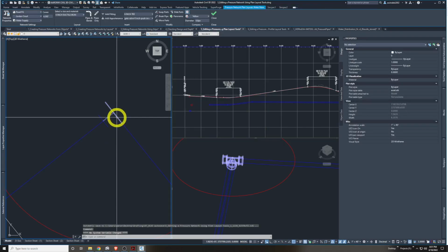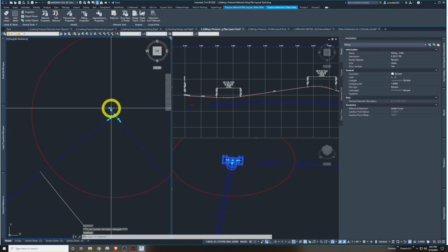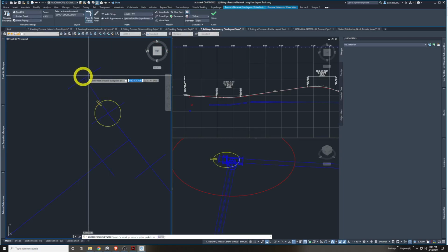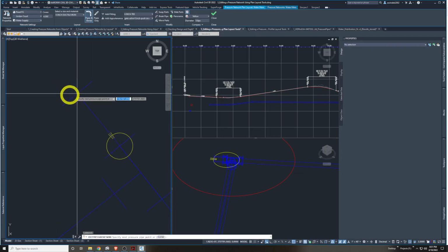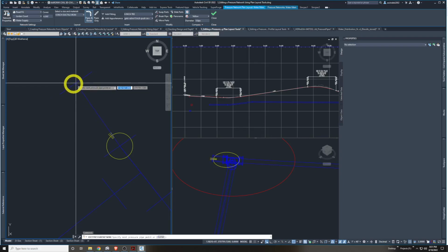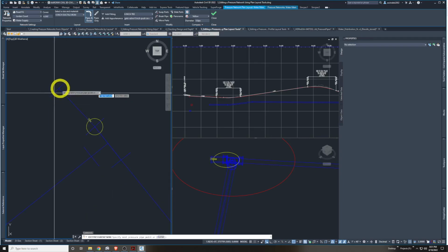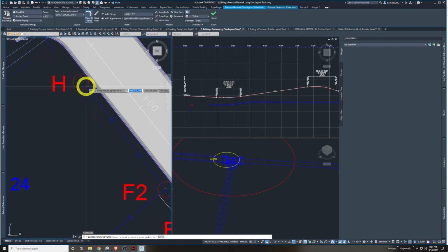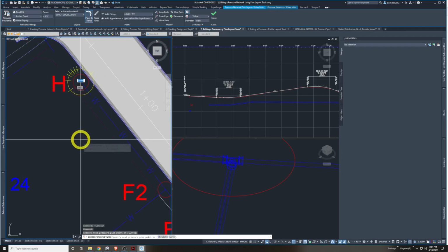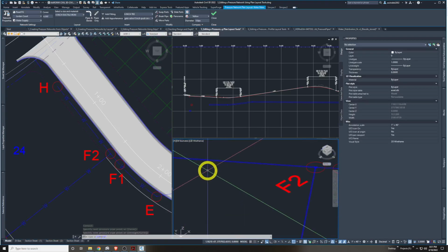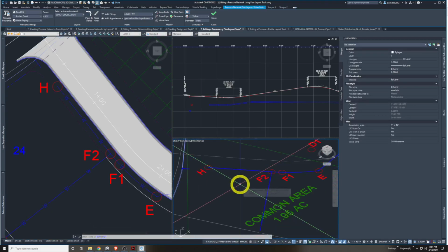We'll try one last item here in this T we just made. Let's check out this plus sign, and this continues the layout from where we last left off. It'll add a pipe. So that's really handy. Now we only have so many options here because we have a T fitting which doesn't have as much deflection. So this is literally only calculating in the small amount of deflection we have for the pipe itself. Let's go up to H to the center, hit enter, and that continued on our pressure pipe network up to H. That's it for this area.